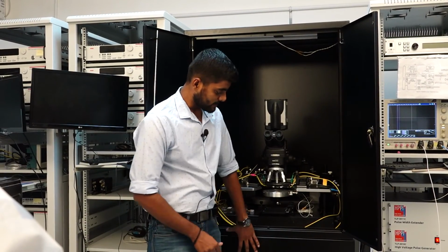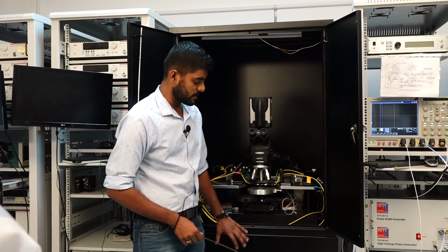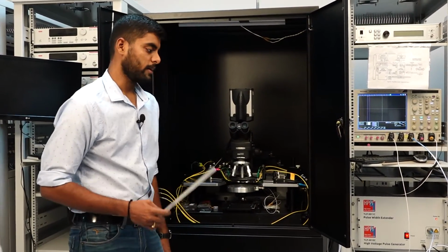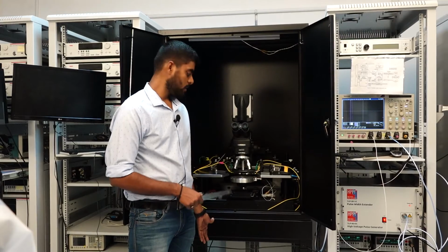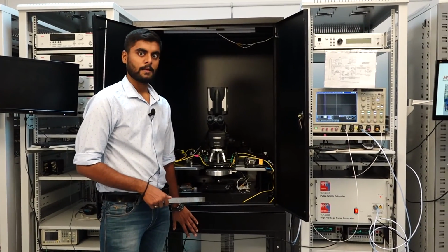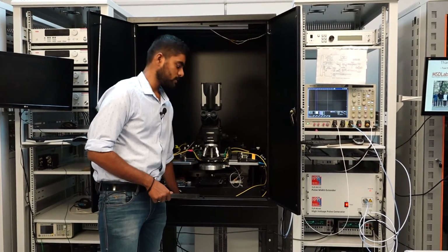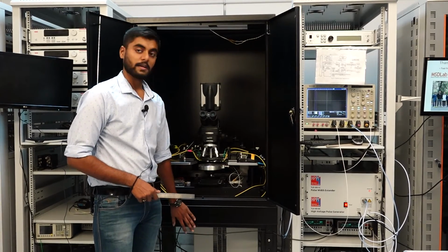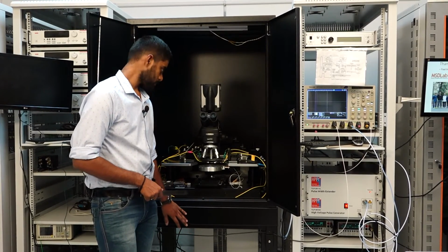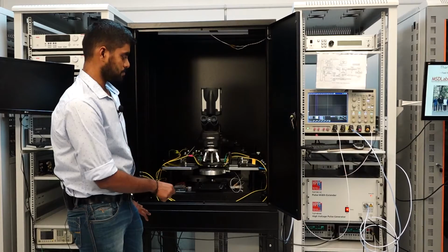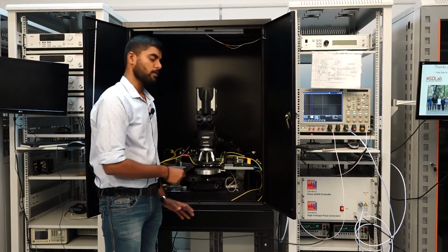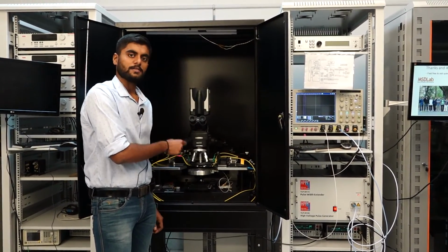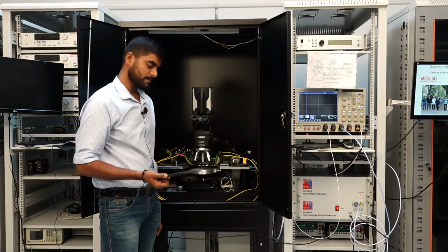Then you'll see that this whole probe station is standing on this kind of a cushion. The reason I'm calling it a cushion is because it is actually a cushion filled with air. So whenever you push this whole assembly down, the devices will not experience any turbulence, because then you are sitting on a chamber of air. So then this is the major component of the probe station. This whole assembly here is a microscope that is used to view your devices under test.